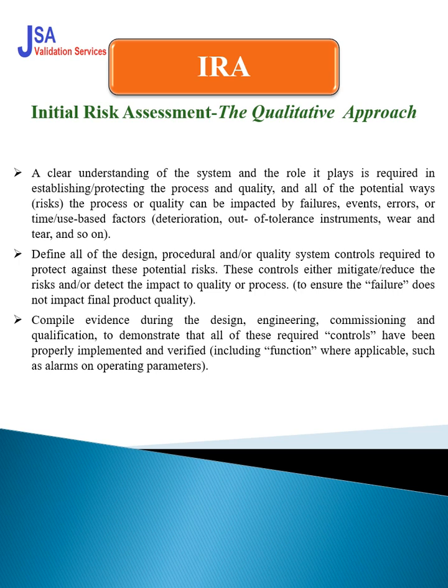In your design specification or in the URS you have mentioned this requirement, that you require an alarm system, you require dew point indications, you have the dumping process. So that should be challenged in either IQ or OQ or PQ. You have to challenge these implementations. Suppose you are saying yes, we have this procedure. So where do you challenge this procedure? That is very important. So every risk you identified here and every control you mention here to mitigate that risk should be challenged in the design, engineering, commissioning and qualification.